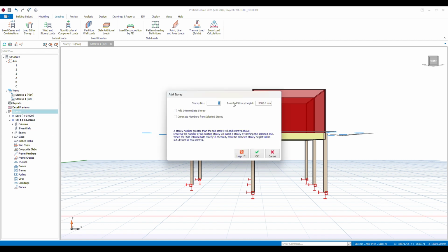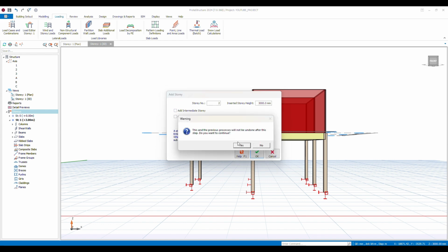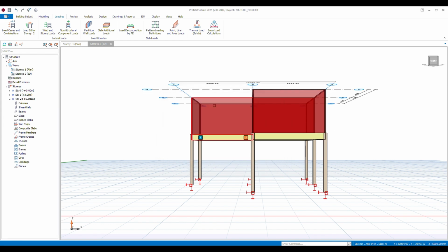So we set the maximum number of stories we're going to have, that's 2. Yes, it creates another story. Because the story is similar, because we're just going to have a beam above, we're not going to have a floor, so the frame is similar. So I could just import the columns and the beams to that level, neglecting the slab because there's going to be a roof there.